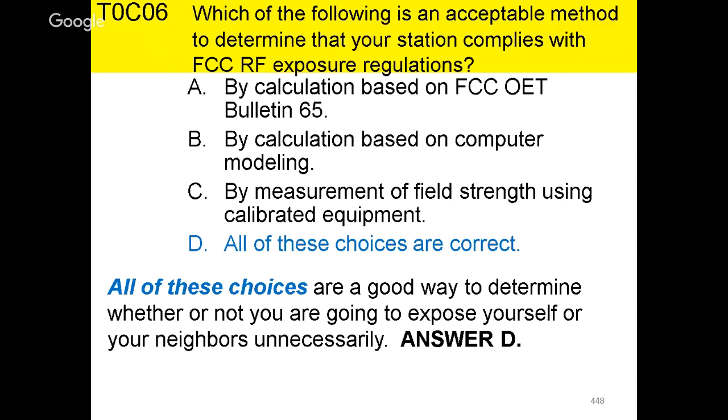And you know, it's not unreasonable for somebody to put an antenna up on the corner of their house and to have a 50-watt beam antenna only 20 feet away from the neighbor's bedroom, and you should at least be aware of what you're doing. Or another good example, you've got a 100-watt amplifier in your car, and a 5/8 wave antenna on your roof, and you and your buddies are all hanging out around your car, and you're transmitting, only 3-4 feet away from people's heads.